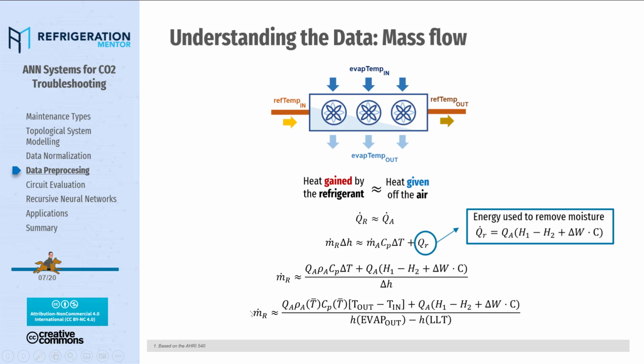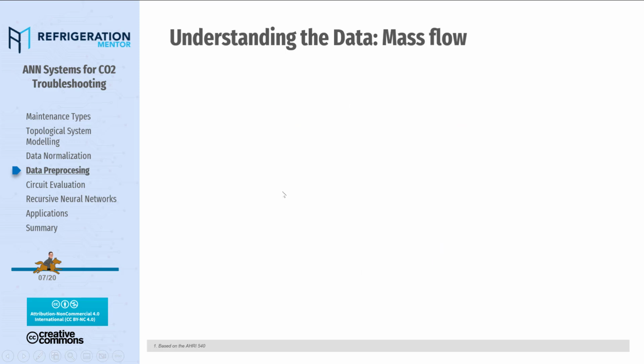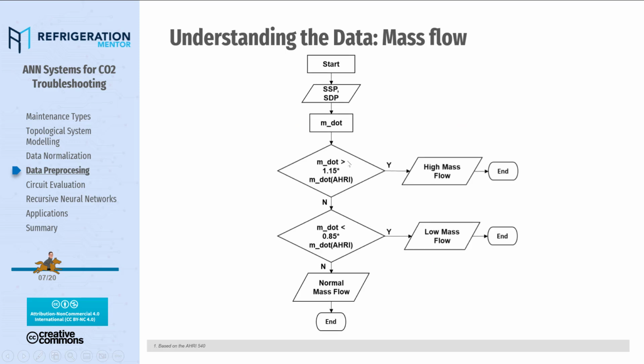And the difference between the mass flow required from the evaporator and the compressors can give us some practical information. For example, differences in the mass flow will end in problems such as leakage, fluid back, and maybe evaporator core blocking. And on the other hand, the lack of mass flow will end in problems such as inadequate heat transfer in our cold room.